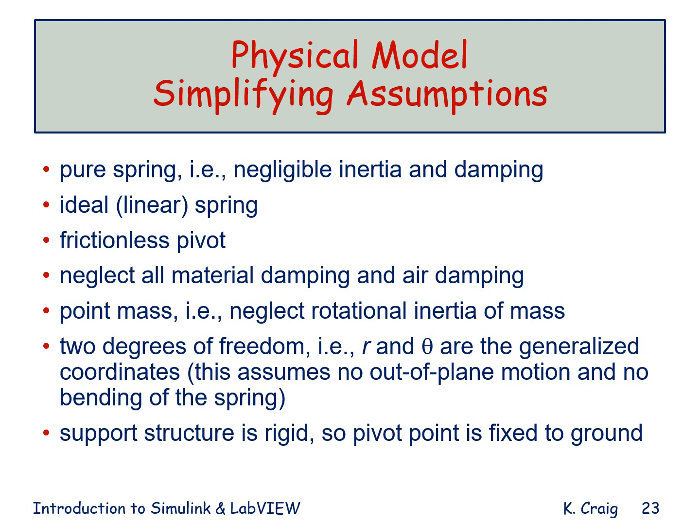Even though the mass at the end of the spring, as it goes through its motion, does not maintain its orientation, so the motion it is performing is really general plane motion as it is translating and rotating, we will neglect the rotational inertia of the mass. We will treat it as a point mass. This simplifies the equations of motion considerably, and we can always revisit our simplifying assumptions at the end when we compare our predictions to our measurements and try to understand any discrepancies.